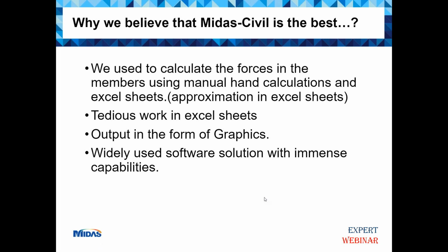You have to get the shape function, derive the element equation, get the stiffness equation, and given such a bridge that we have, then you have large matrices, then you have to use the Gauss elimination method, if it's the one that you've chosen, in order to get the primary unknowns, and then you start interpolating the results to get maybe tabulated data or graphical data. By the time you do all that, you will have taken almost a week in just analyzing a very simple element or a very simple structure.